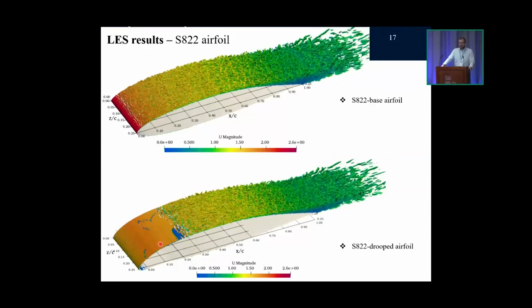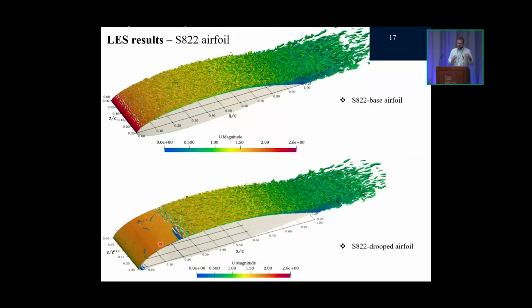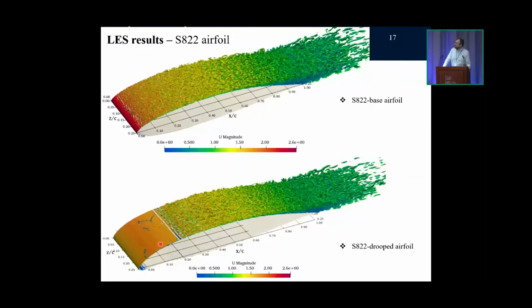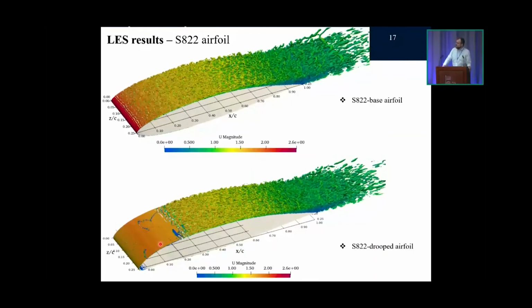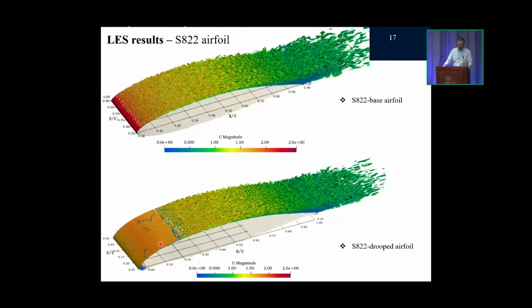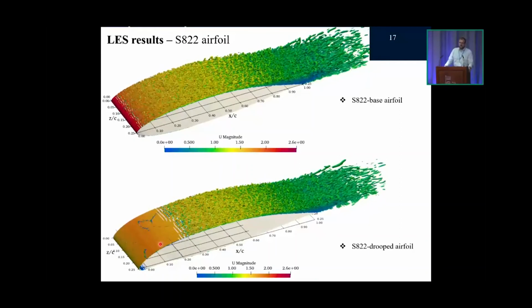After which we do see these span-wise structures being shed. They shed downstream. There's some interaction. They live longer, in terms of there being more periods of those. They begin to break down into three-dimensional structures and then continue to evolve. And by around 60 or 70% chord, the turbulence is similarly developed.